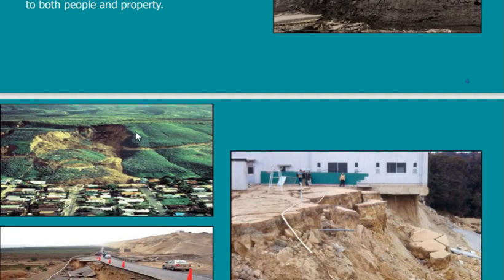So if I want to study the stability of this slope, I have to keep in mind the shape of the failure, to study the stresses that would happen at the interface between the part that will fail and the remaining part. I have to study these stresses or forces, and once I know them, I will know the force that would cause failure.